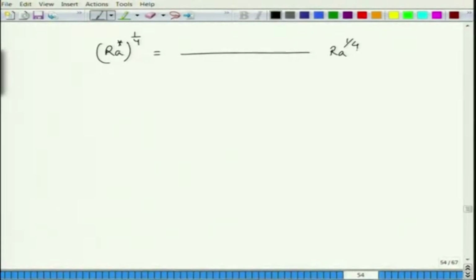Okay. And what is the conventional Rayleigh number? So, let me write it here first. The conventional Rayleigh number is nothing but the Grashof number multiplied by the Prandtl number. Okay. Grashof number you know for natural convection, and Prandtl number is the ratio of the viscous diffusivity and the thermal diffusivity, right.